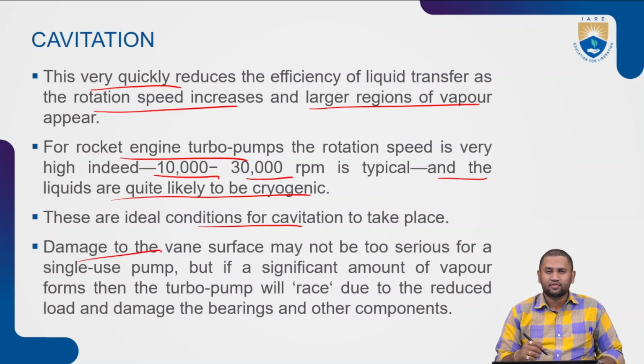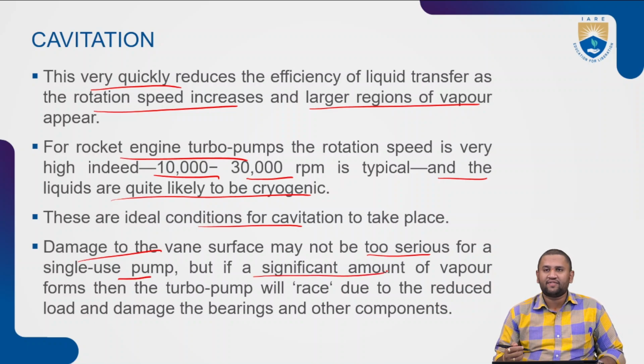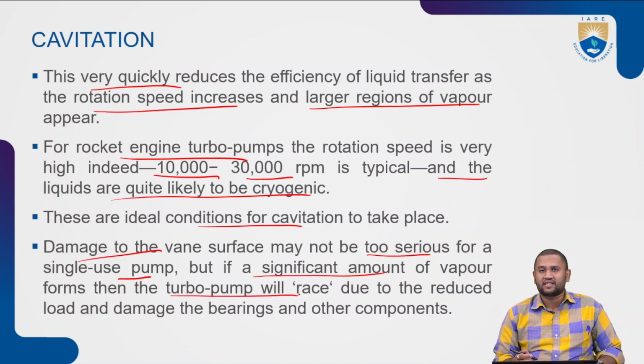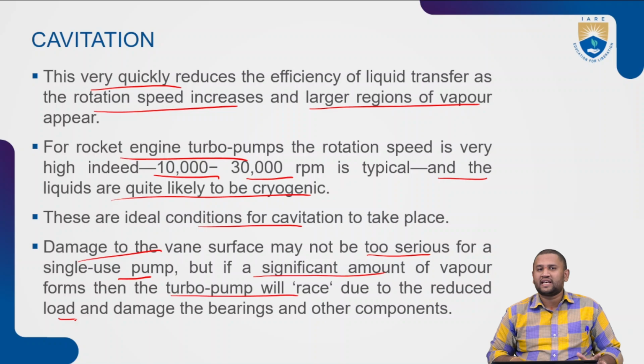Damage to a vane surface may not be too serious for a single-use pump, but if a significant amount of vapor forms, then the turbopump will race due to its reduced load, and damage to the bearings as well as other components might take place.